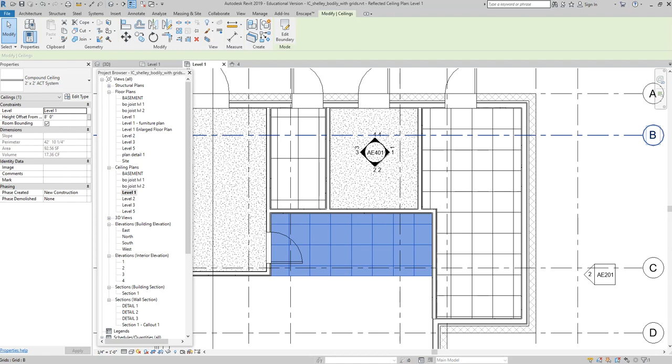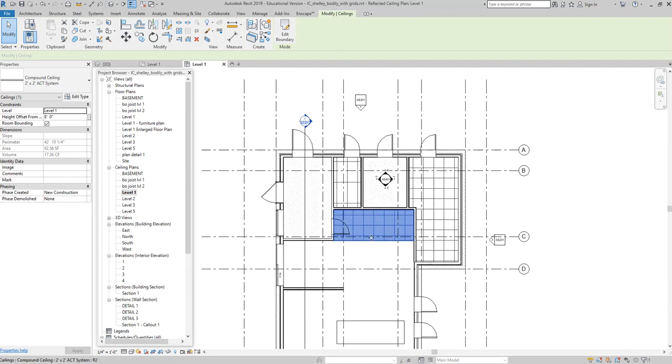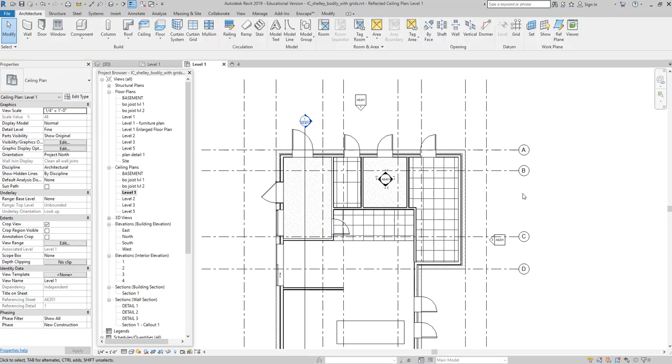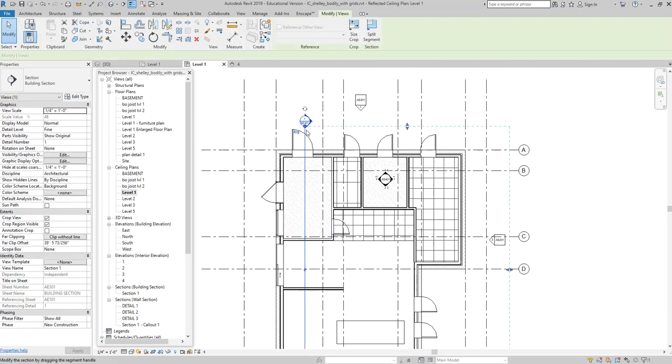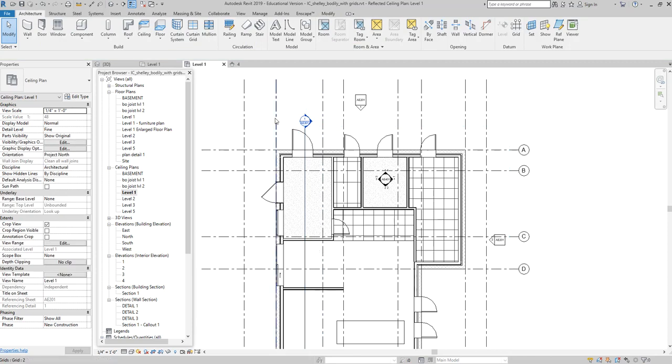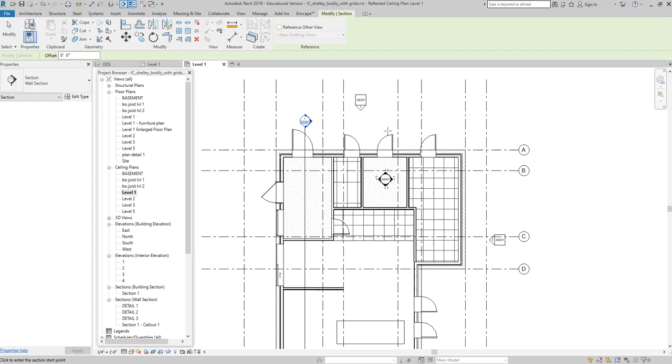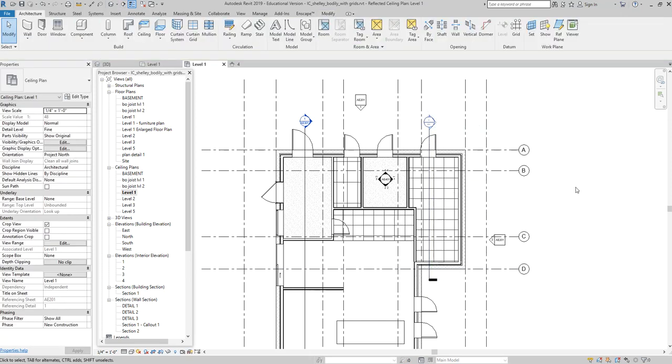You know how to edit the assembly of our ceilings. Number one, we can place them at whatever height we want to place them at, right? But if you want to have some help lining these ceilings up, draw a section. We talked about drawing sections. It's very easy. Section, click. You'll see me drawing sections in my model that I never intend to use again. I use it to help me get my geometry where it needs to go.